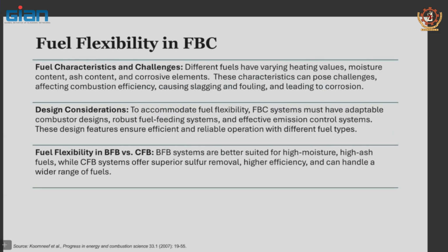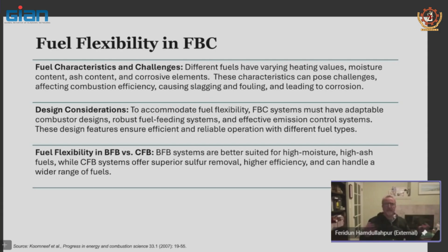Let me just talk about the design considerations. To accommodate fuel flexibility, our CFB system must have adaptable combustor designs and a robust fuel feeding system. That means it is adaptable when you have different types of fuel coming: one day it's pure coal, the next day it is mixed with municipal waste.